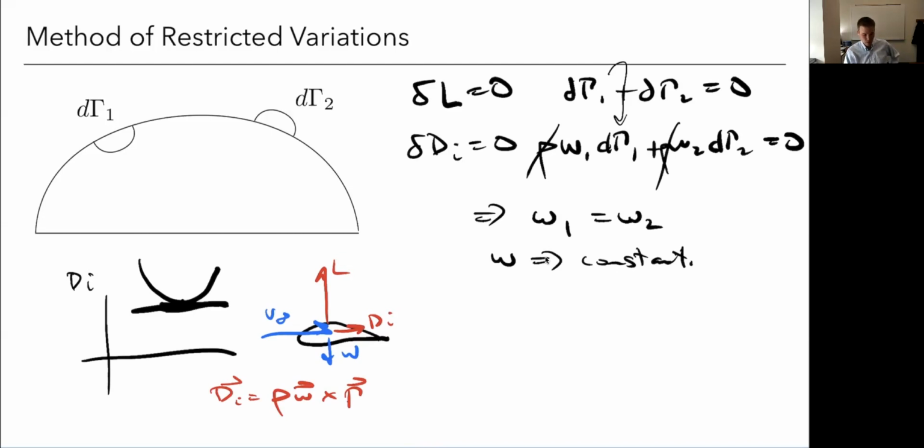So for example, let's imagine I have a non-planar wing. So here I'm going to increase the dihedral, perhaps all the way vertical, like in this case, so I've got a wing with a winglet. Well, let's look at what a winglet does. So one thing that you'll sometimes hear, let's use the Kutta-Joukowski theorem a few times here. So let's say this is a back view of our winglet.